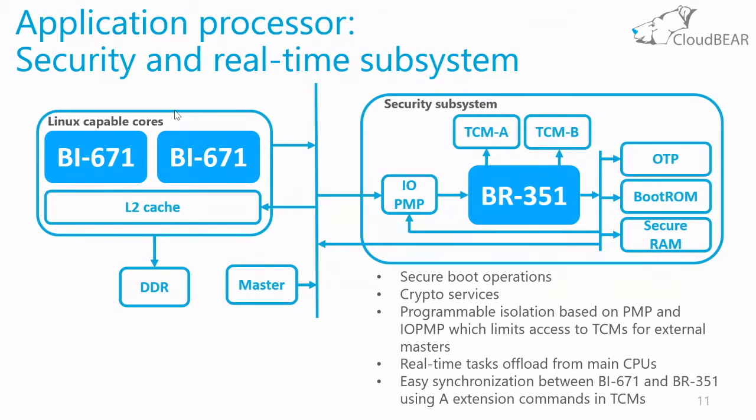The isolation is based on IOPMP, which limits access to the TCM memories of this security subsystem for external masters. Besides security work, this core can do real-time tasks to offload them from the main CPU.